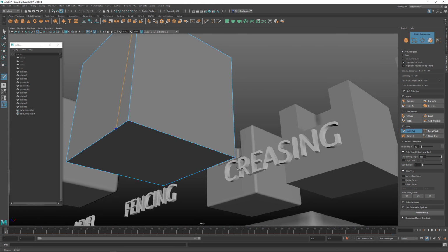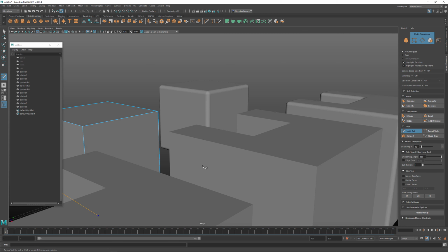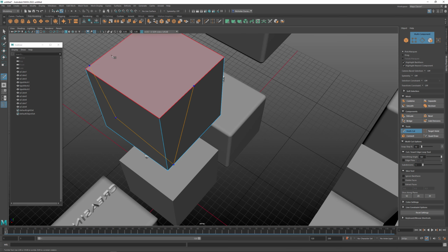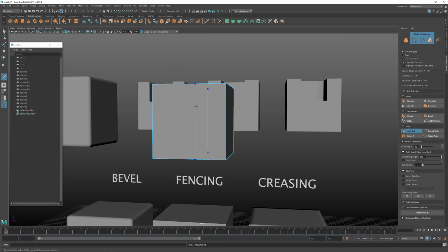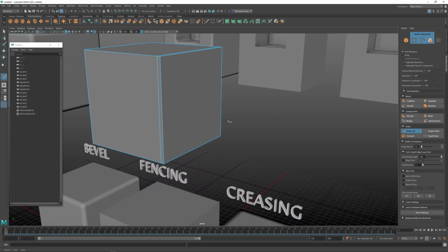And while I drag out on this, you can see it's got numbers on here. If I hold down Shift, I can snap to these different increments within here like that. So this is if you want to not do something that's going all the way around the model. If I hold down Shift, again, I can snap to 50% of this, and then I can click and then drag out on this edge and then snap back to that original point right here like that, and then hit Enter. And so I made a really bad cut there just to show you how that tool works. But if you hold down Control, you can just do an edge loop across the entire geometry, as long as your geometry is sound on there.